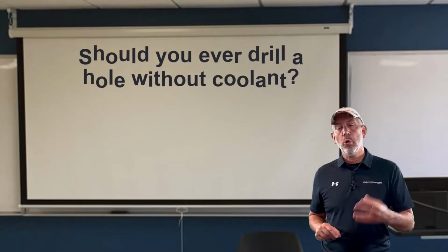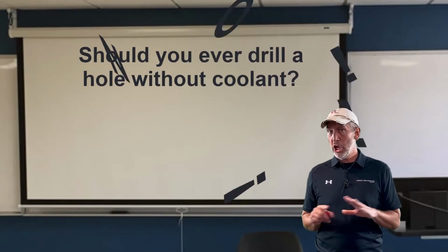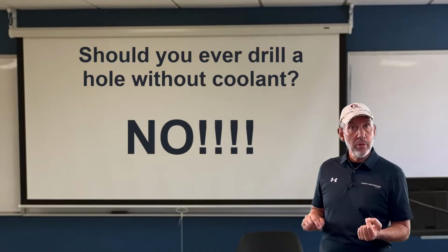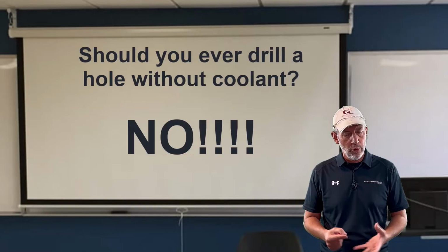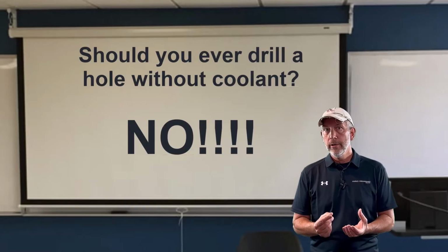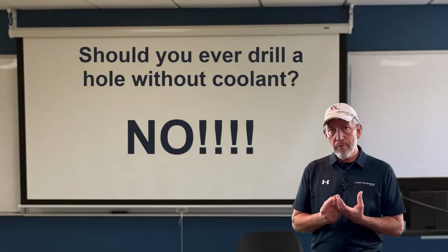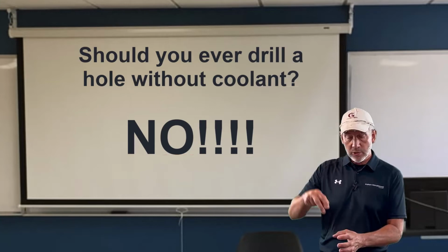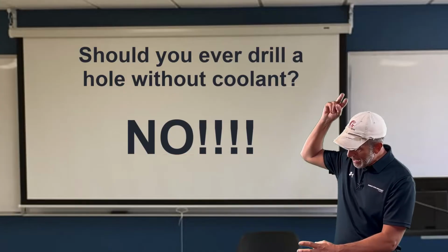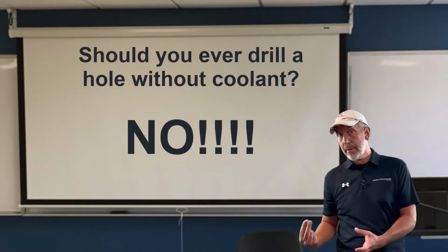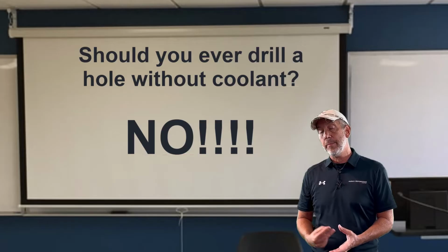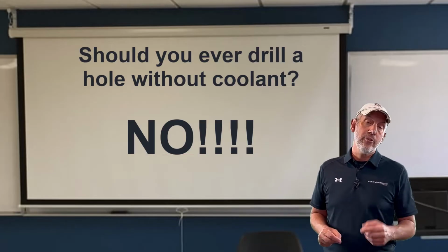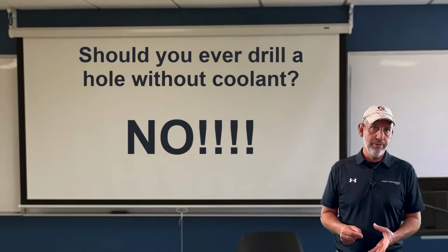Should you ever drill a hole without coolant? No, no. Always put coolant in your hole. A drill, believe it or not, is the fastest metal removal tool that we have. It's going to remove material faster than anything else we can do. That generates a lot of heat, right? That's why coolant through on carbide drills is great. Blast that coolant all the way down to the point. That point's going to get very hot, and also that point is the workhorse of the drill. Understand that. So never run drills without coolant through.